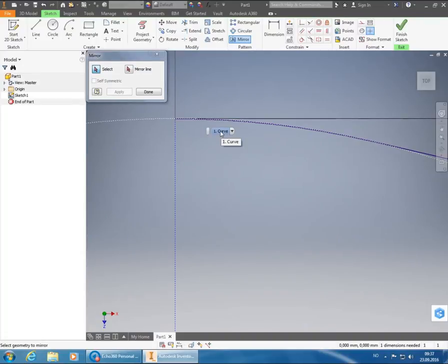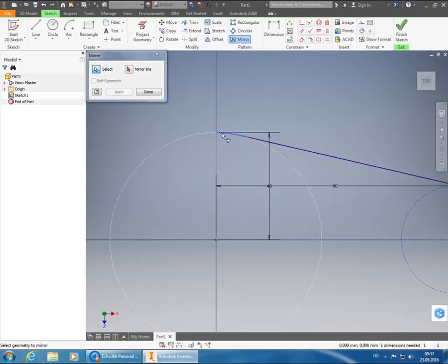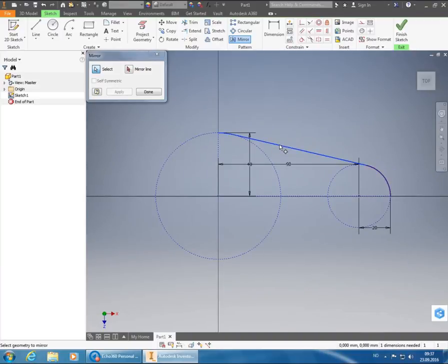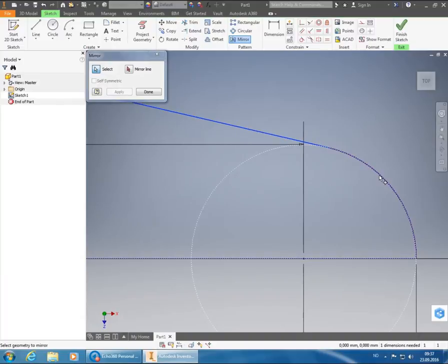Here it wants me to mark the construction circle first off, so I just let it hover for a while, then I open this drop-down menu, because then I can choose the arc that I just created instead. Zoom out. Then I also select the tangent line. And then I go in here, let the mouse hover a bit in order to avoid marking the construction circle. Use the drop-down menu and choose the second curve.